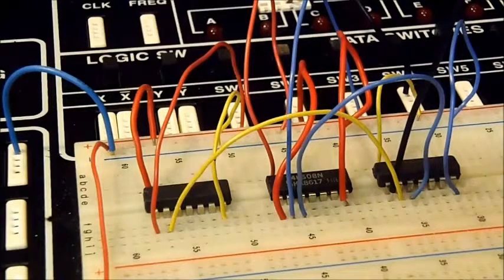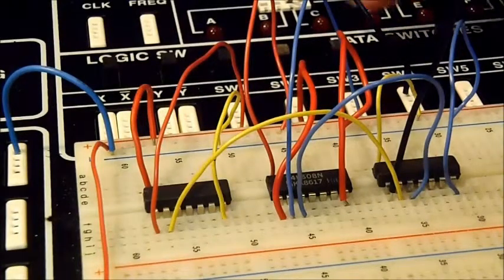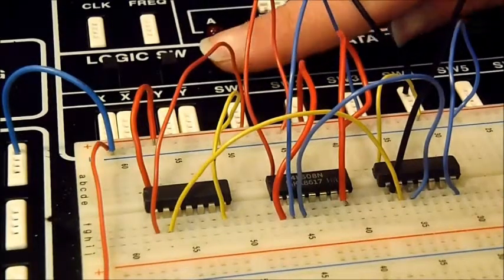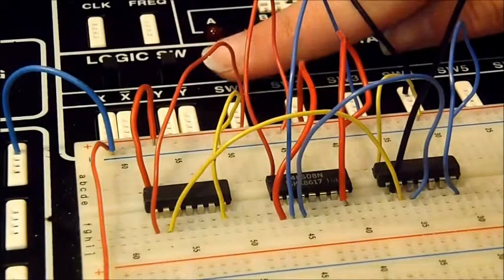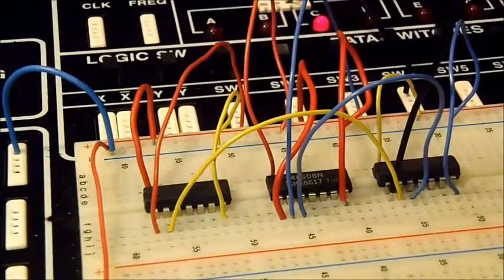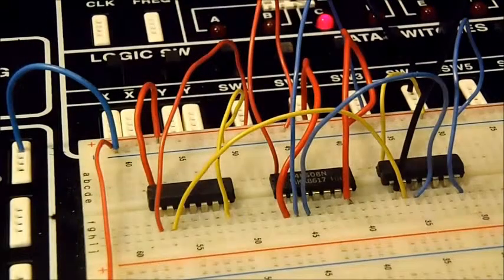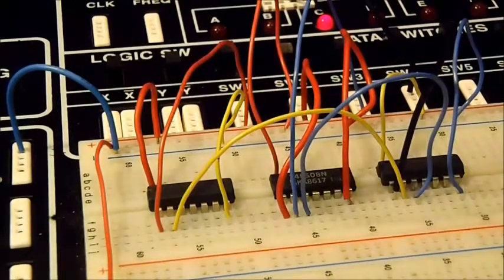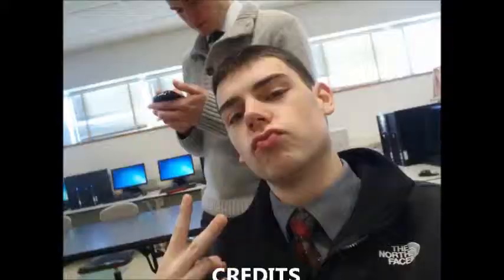Reset the circuit. You turn all the switches off. When switch B and C are off and switch A is turned on, the light will turn on. This shows that we have wired our circuit correctly. Now you can see how we use all these principles to create a new voting machine, using inputs and outputs, AND, OR, and NOT gates, and breadboarding to create a working machine.